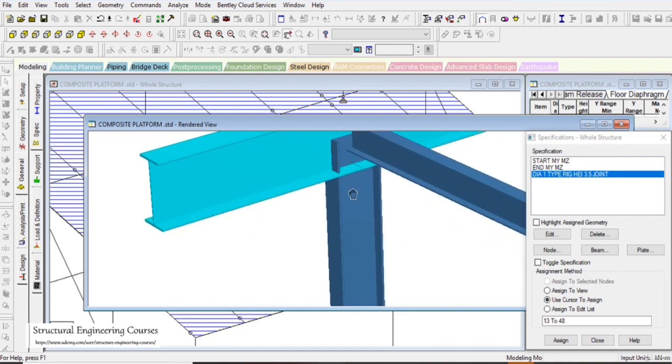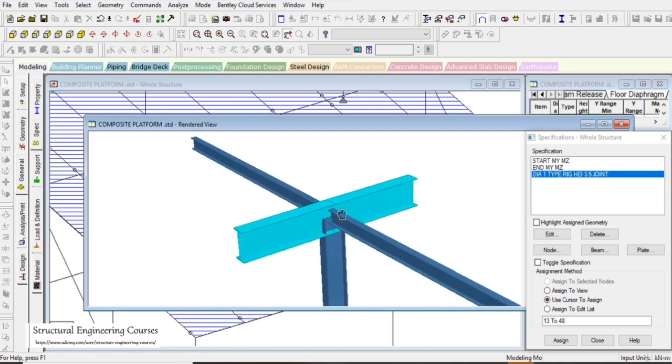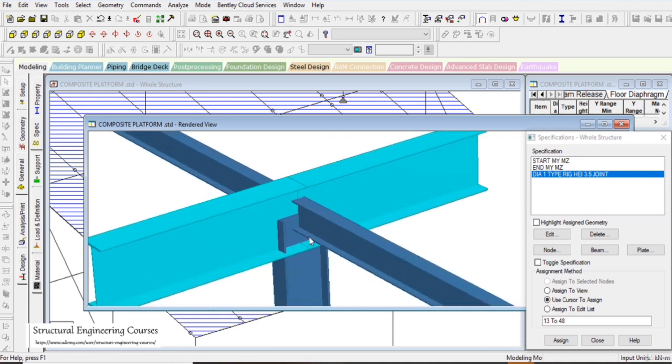That is, this I beam is going inside this column here, and the one more problem is that column is not even going on the top here. The beam is different, column is different, the beam is going inside the column. So all these things needs to be resolved with the help of these specifications itself.